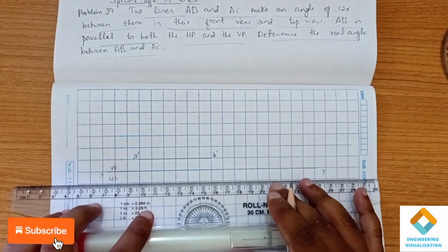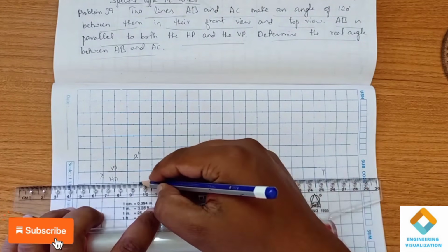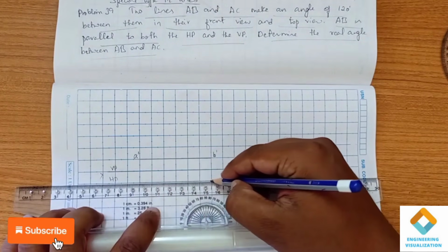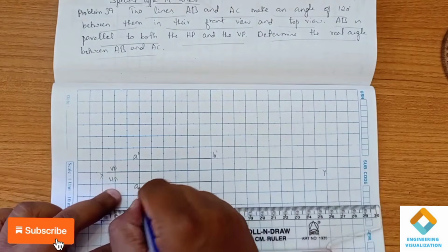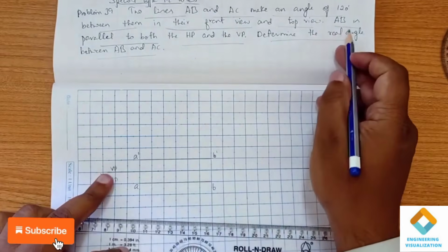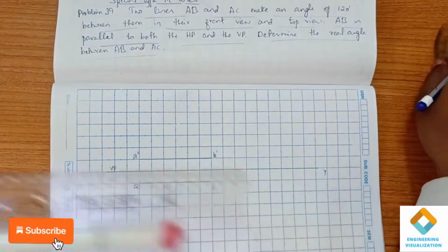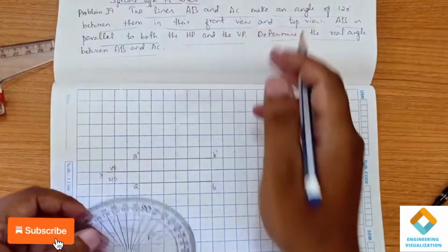In the same manner here, parallel to it, because the AB line is parallel, here I am considering 60 mm. Okay, so this is B. So the line AB is parallel to both HP and VP. Now AB and AC make an angle of 120 degree.